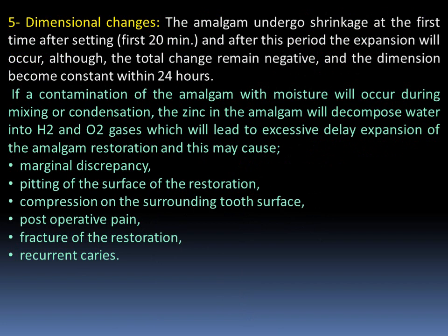Also, dimensional change. The amalgam undergoes shrinkage at first after setting, in the first 20 minutes. After this period, expansion will occur, although the total change remains negative, and the dimension becomes constant within 24 hours.